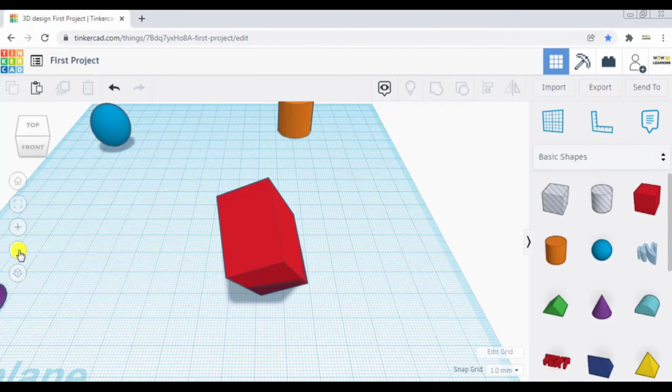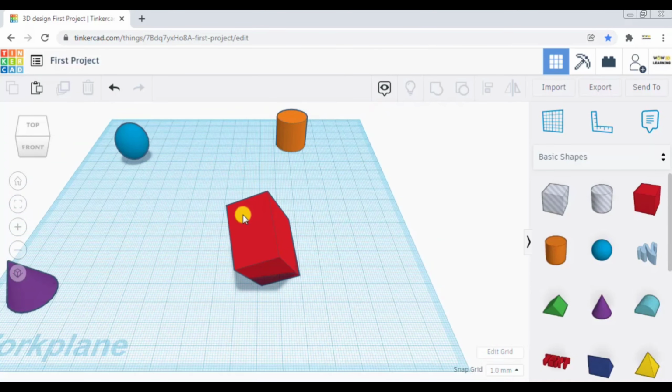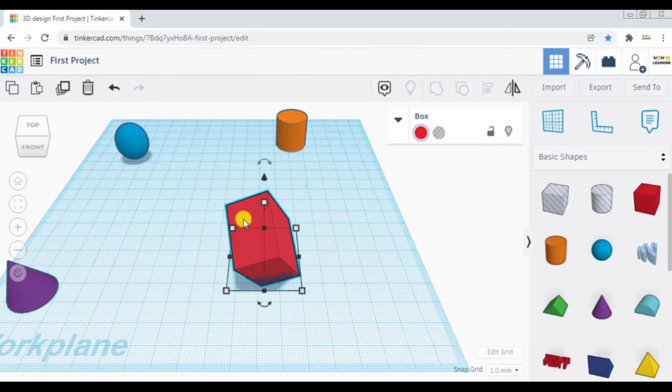Now once you have rotated your object into vertical plane, just remember when you click on the object, when you click on black node in this orientation, this dimension is not the length or breadth of the object, rather it is showing the height of the object as a whole. If I click on white node, you can see this 34.24 is not the dimension of the side of the object, but the size of the object, what it occupies as a net in the given work plane. Now moving on to next, we are going to see some options in the box.